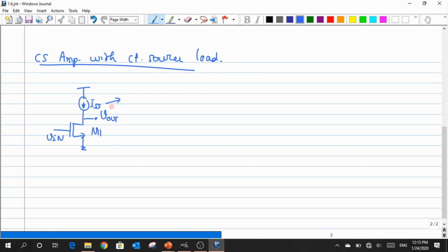NMOS? Okay, let us go with the NMOS, but the source terminal of the NMOS has to be lower than the drain potential, right? So whatever the source potential is, it has to be smaller than the drain potential for an NMOS. So if I do so, whenever there is a swing at the output, what is happening across the VGS of this M2 transistor? The VGS is varying, which means the current is no more constant. I cannot use that. So what type of MOSFET can I use to replace this ISS?